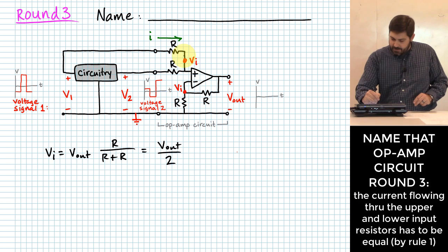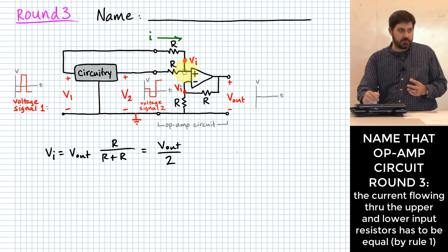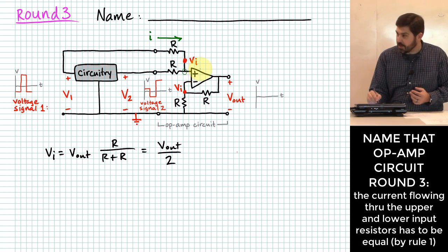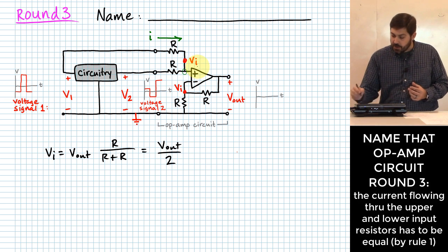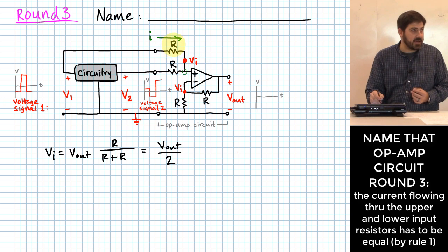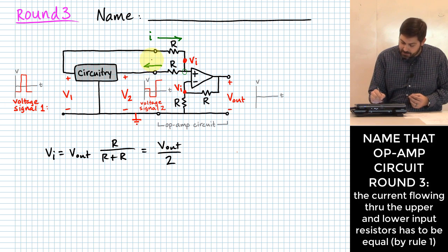It's going to come down, and then it looks like there's a possibility perhaps that it could branch where that I comes down into the non-inverting terminal of the op-amp right there. But does the current actually branch? Okay? It can't, because no current is allowed to go into the op-amp on that non-inverting terminal. So is there another place where I could show I? If I defined that rightward I on that R that's up top, I would say that means I better have I that flows this way too.